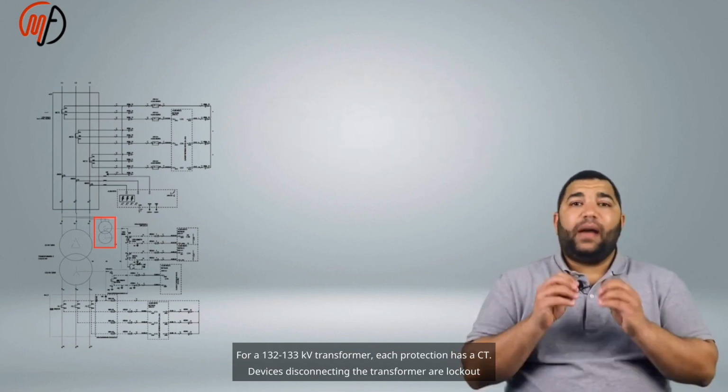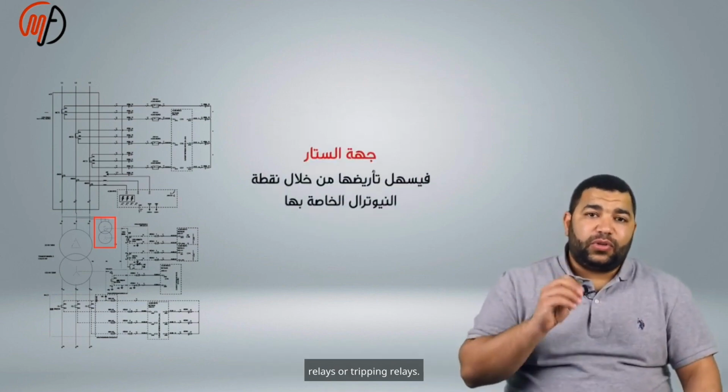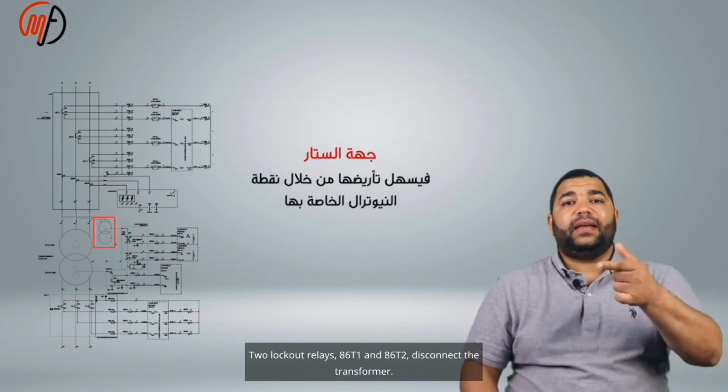Devices disconnecting the transformer are lockout relays or tripping relays. 2 lockout relays, 86T1 and 86T2, disconnect the transformer.